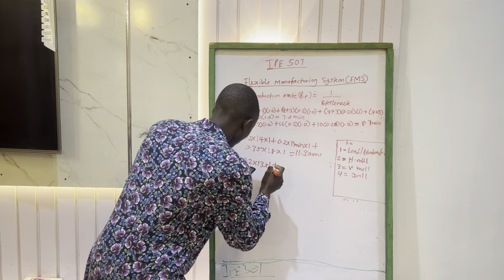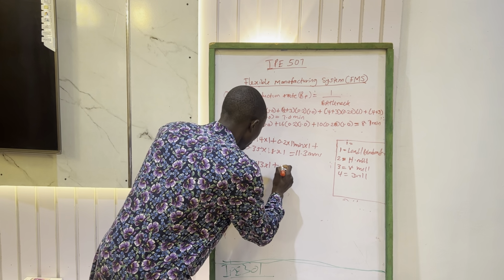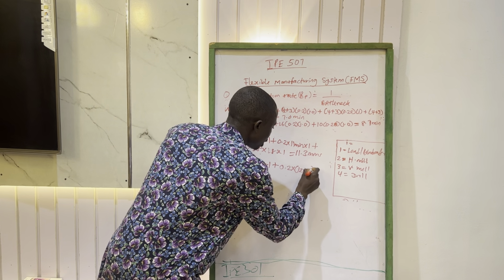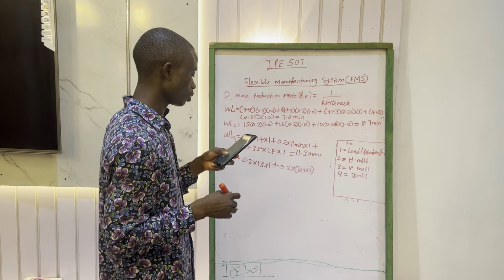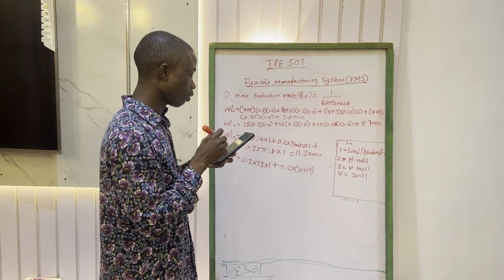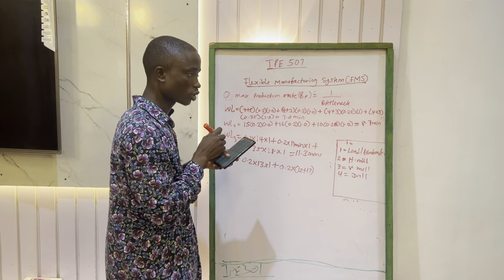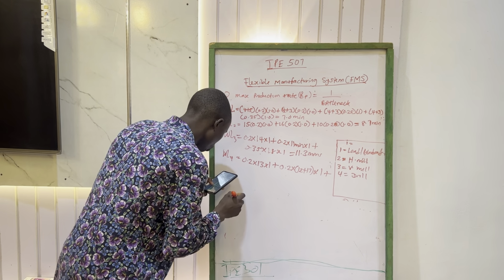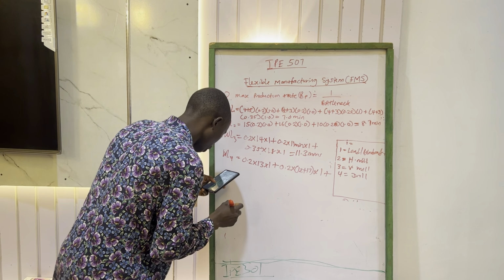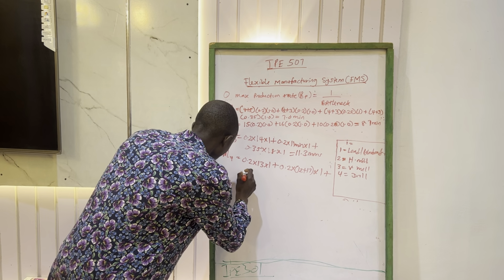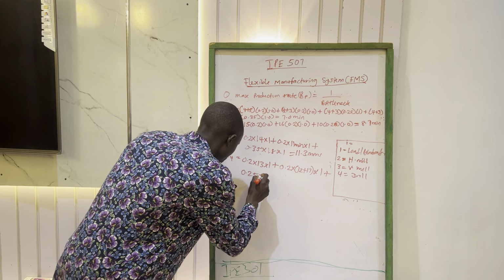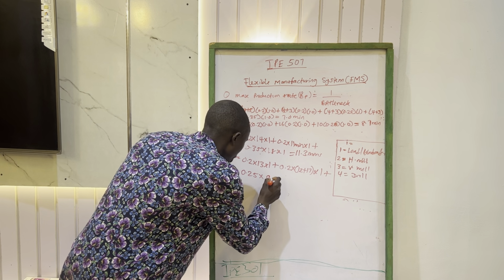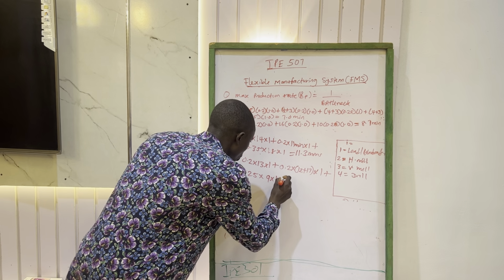Firstly the part mix, which is 0.2 times 12 plus 17. That is total operating time for drill in product B. So times 1 plus, we move to product C. There is drill in product C as well, but the part mix is 0.25 times, the time is 9 minutes and the operating frequency is 1.